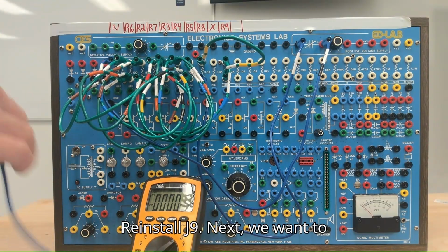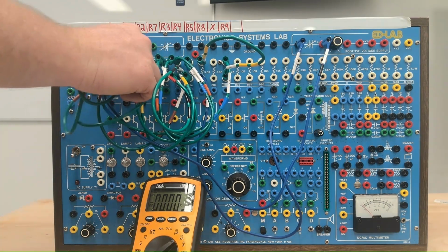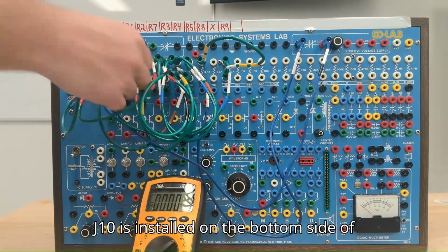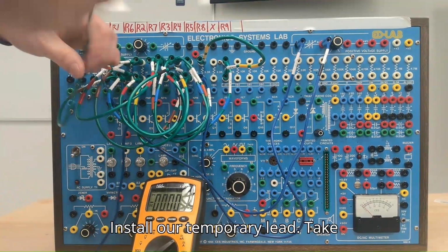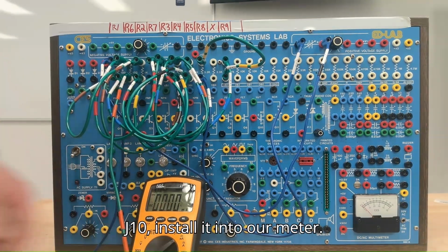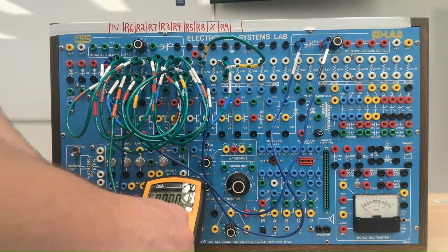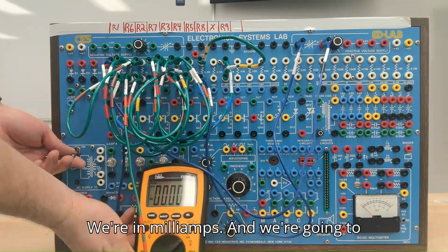reinstall J9. Next, we want to find the flow of current through J10. J10 is installed on the bottom side of R7. Let's install our temporary lead, take J10, install it into our meter. We're in milliamps, and we're going to turn on the trainer.